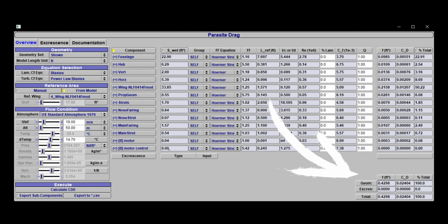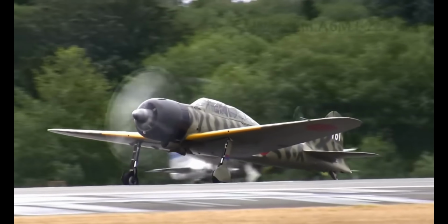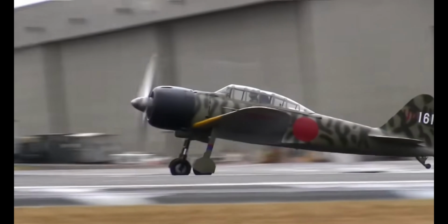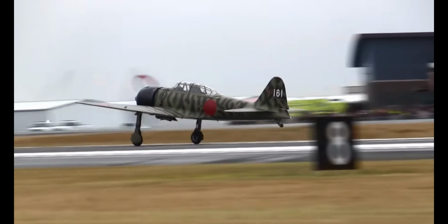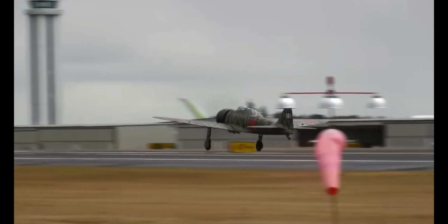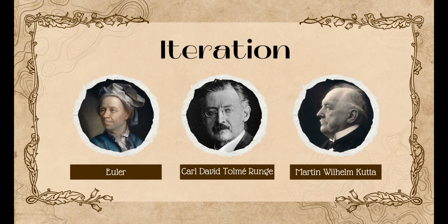With the takeoff equilibrium equation as a reference, all the parameters are now defined and can be used in the takeoff performance calculation. The simplified takeoff model is treated as a two-dimensional motion with variable acceleration. During the increase in speed, lift, drag, and friction forces are constantly changing, so an iterative approach is applied for the calculation. I used both the Euler method and the Runge-Kutta method as a double validation to compare the results.